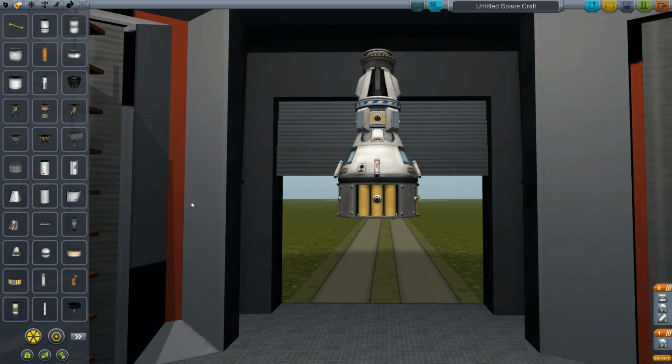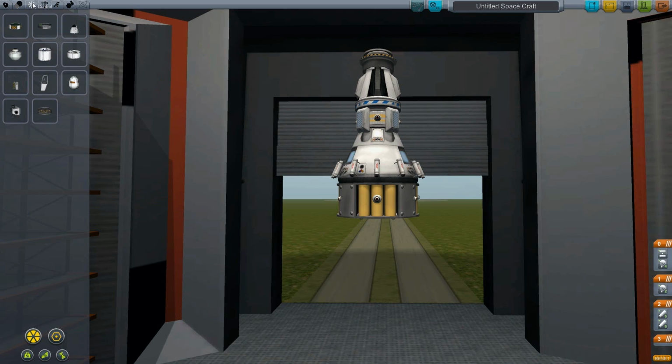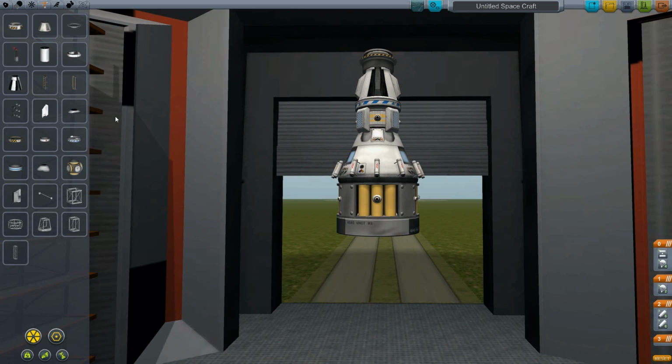And then beneath that is actually like an adapter for the retrograde, like the retro package. It pretty much had a retro package similar to what Mercury did, except it wasn't really strapped on to the bottom in the same manner that the Mercury capsule's retro package was. And then there were also maneuvering thrusters in that next retrograde section. So you had the maneuvering thrusters for re-entry on the top, but the actual attitude control thrusters were on the bottom. So I've got two sets of thrusters there.